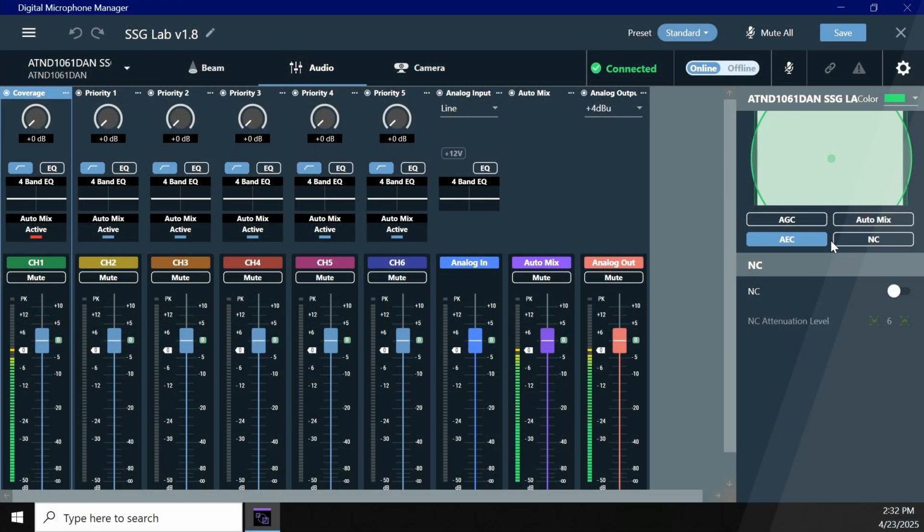And then finally in this processing, we have the AEC, your echo canceller. So that's built into this device. Now, it's a little deceiving when you look at this because there are very few controls, but it's actually a very powerful AEC built underneath. It has a tail of 400 milliseconds, which is a very long tail and a good size for processing.